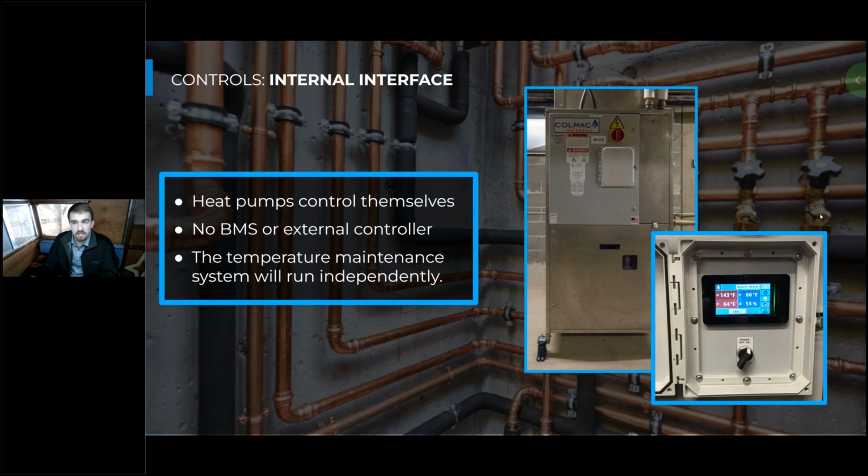The downside to that is in this system, the rest of the system is blind to what the heat pump's doing. So if you're looking at remote troubleshooting or you want any kind of feedback from your system, that's going to be harder to get here because all the controls and logic are just on board the heat pump and usually not very transparent. The sequence itself is not very transparent if you're just looking at the heat pump.